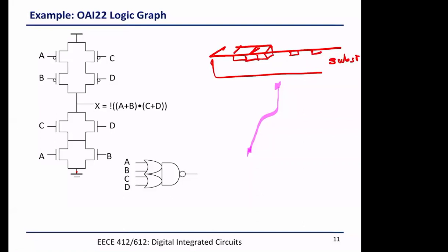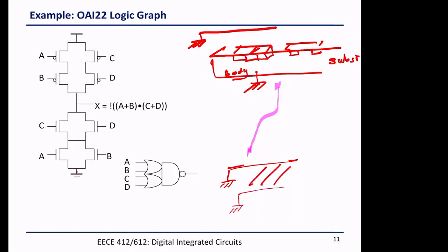The different transistors occupy substrate, it represents the body, and the body is grounded. So any metal wire above that is connected to ground, I am effectively looking at the capacitance between ground and ground. This is like a resistor from short to short, it doesn't affect anything. So a capacitor from ground to ground is not a problem for me.